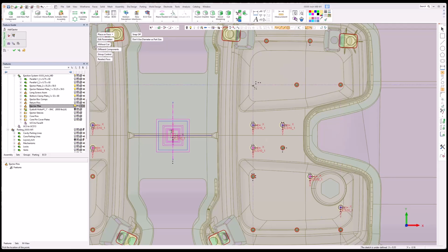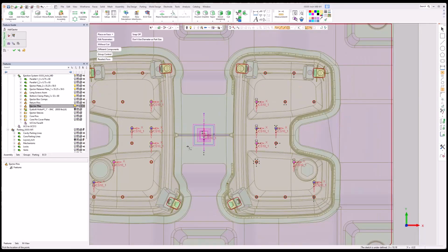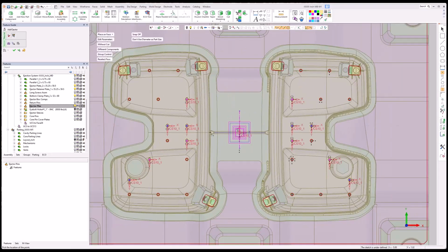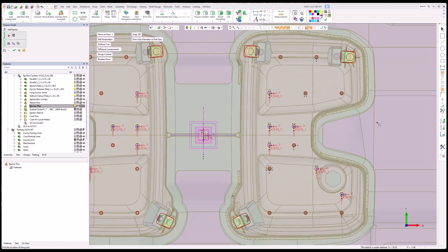And we'll put another one up here to balance. Okay. While I've been adding those pins on this side, they've automatically gone to this side. A couple things to be careful of. If I'm referencing things like I have, don't use the snap on or off feature. I find that can give you some cyclic dependency later. Could give you, again, some problems down the road. So I really try to minimize the snap on, snap off feature here.